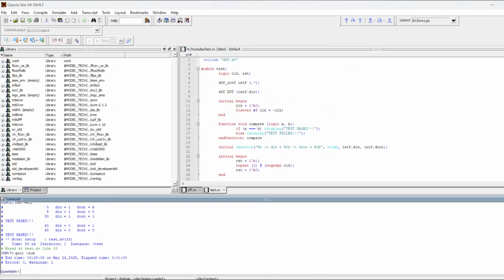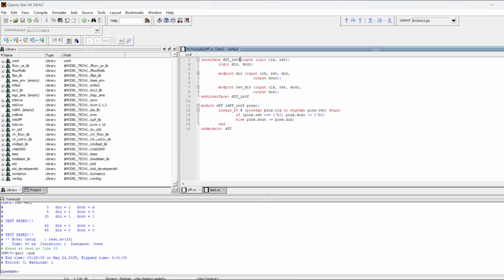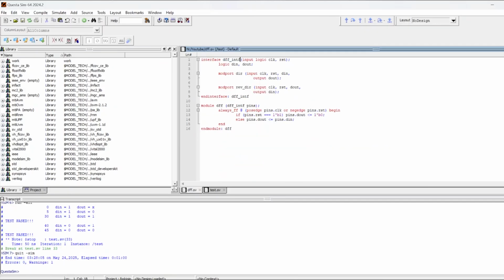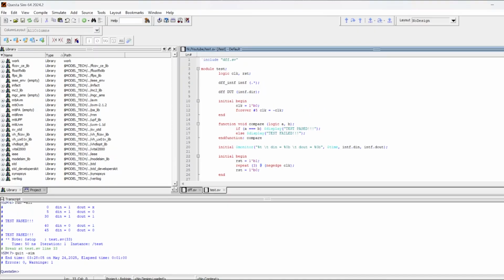With the explicit declaration, you could do more, like in this case, we will be using the particular mode port that is direction, dir. So I could also mention that particular mode port right here. If I mention it here, I do not need to mention it during the declaration of the instance in the top level module.